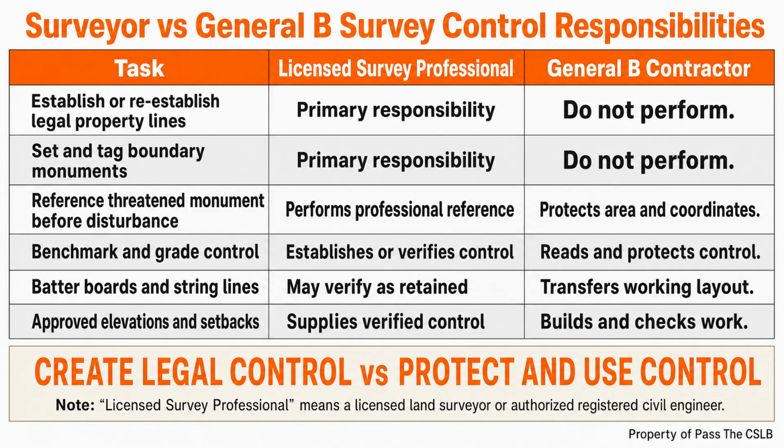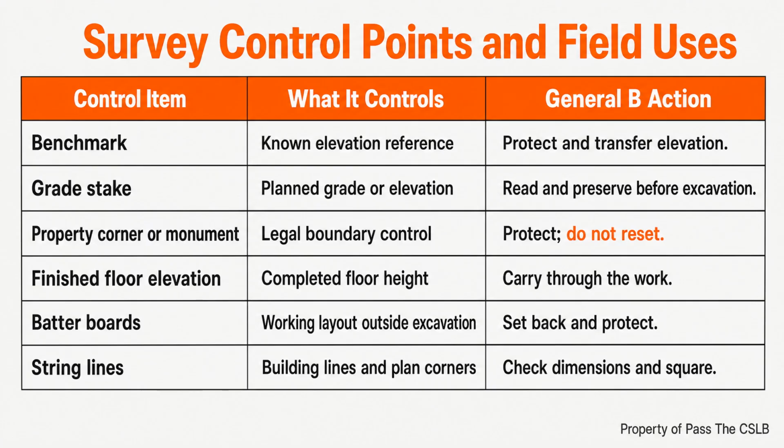Finished floor elevation is one of the most useful ways to understand the chain. The benchmark is the stable reference. The survey or approved layout relates the finished floor elevation to that reference. The contractor then carries that elevation through excavation, forms, foundation work, framing, and site grading. A missed transfer early can keep showing up later because every following operation builds from the same starting elevation.